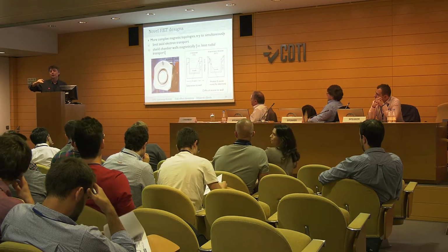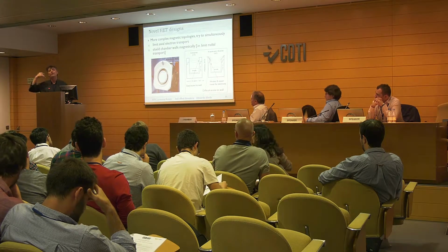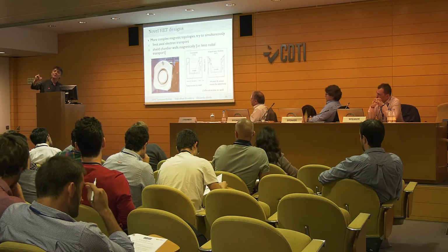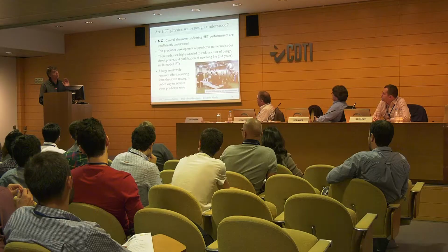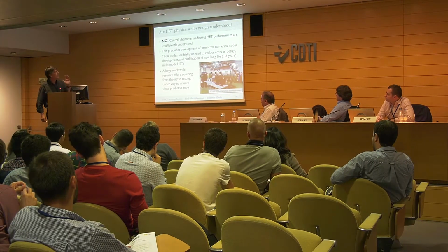We have certain instabilities. They are called the breathing instabilities, the ion transit instabilities, and all these instabilities cause oscillation of the currents and of the voltages that we have inside the plasma, and this must be solved by the electronics people. Say, okay, we have this problem, try to solve it. Try to put a filter there, solve this oscillation, because we cannot control the plasma, okay? The plasma is not such a nice guy, and we have this oscillation, okay? So all these issues, mainly anomalous transport and plasma wall interaction, are critical.